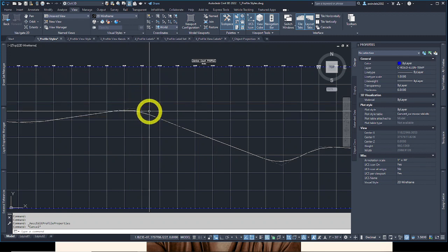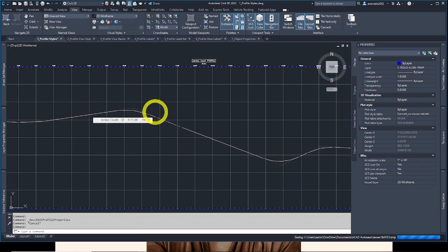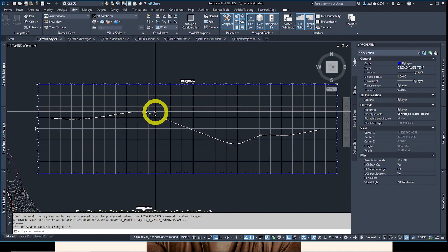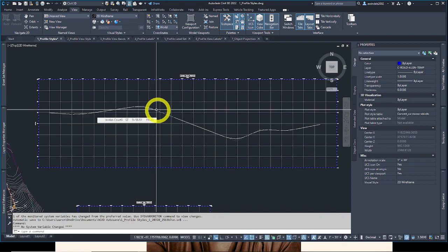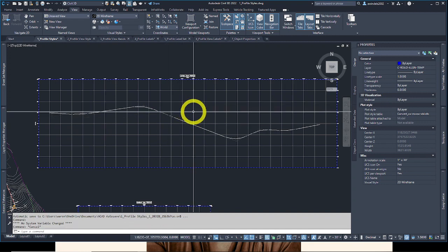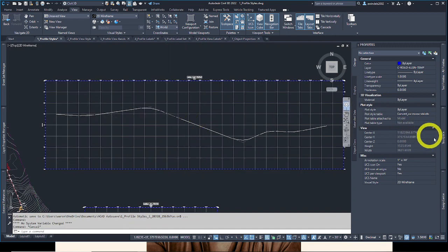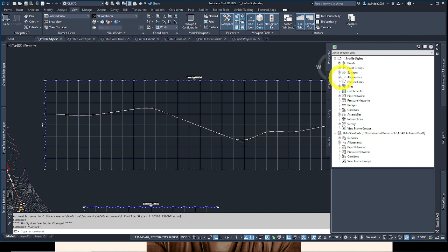Changing one style like I did, it's amazing how many users don't know how to use this. Not trying to make a joke on that, really. Oftentimes it's easier to turn them off temporarily than to freeze them with some of this stuff. It's easier and quicker to control the visibility by changing it to a no display style. So just remember that for a lot of things. It's still in the drawing, of course.